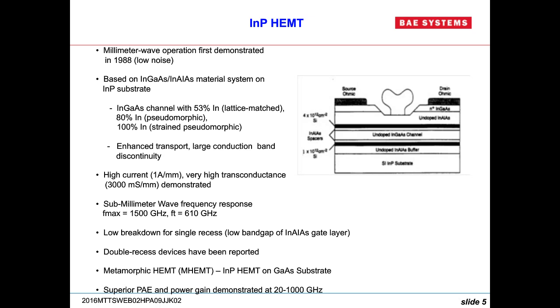Higher indium and higher enhanced transport of electrons, larger conduction band discontinuity, very high current, very high transconductance devices demonstrated. And this is like the device with the highest frequency response that's in use today in terms of solid state, with Fmaxes of 1.5 terahertz.